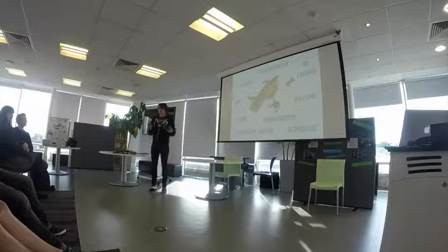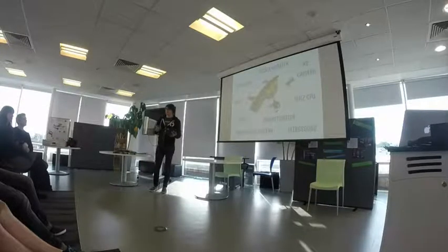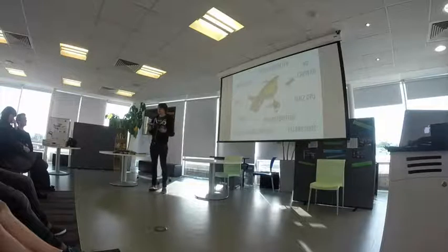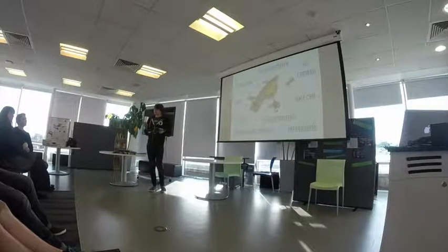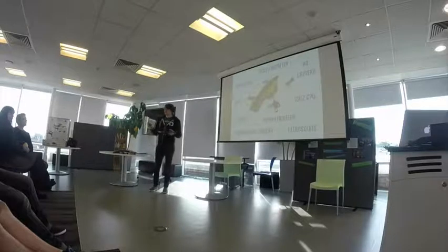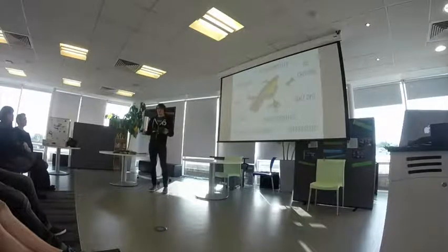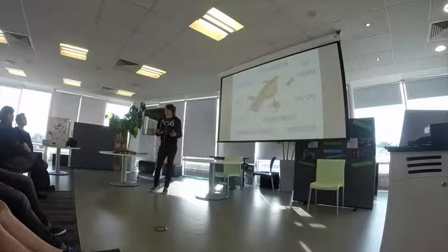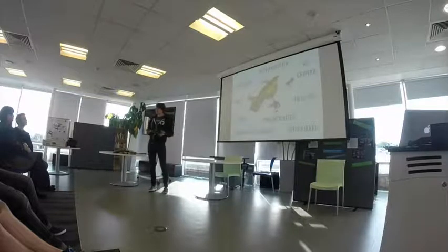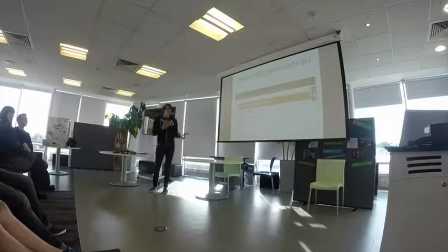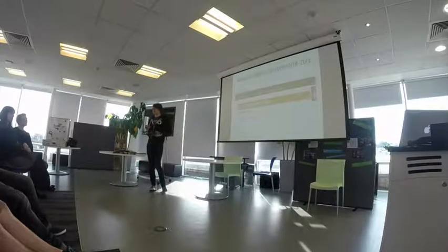When you plug it in, it just boots up and shows up as a Wi-Fi hotspot. So the idea is you connect your iPad or your iPhone to it, and it exposes an API over a UDP socket so you can send it commands and stream video back. But it also means you can connect your laptop to it. You can even connect other devices or drones to other drones, because if you start thinking of it as a router that happens to be able to fly, you can do all kinds of things with it. And Parrot have documented this interface that it sets up, mainly so other people could build iPhone apps.